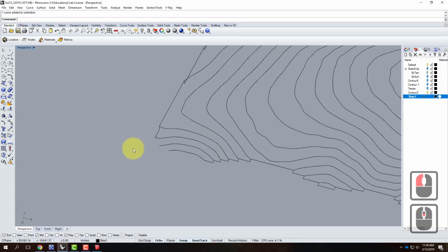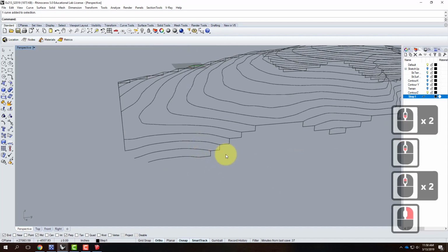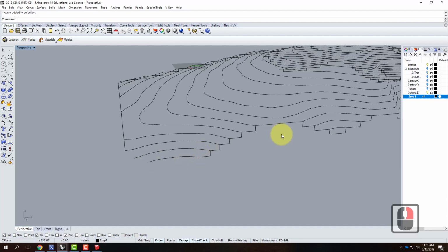So this is the other thing to look for, besides the corners, is to look for places where you either are at the bottom of a set of contours or at the top of a hill. So at the top of a hill, we're going to come up to our contour, and we're going to go straight across and then keep going.